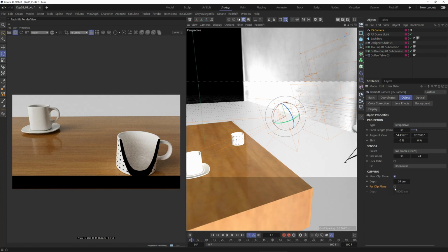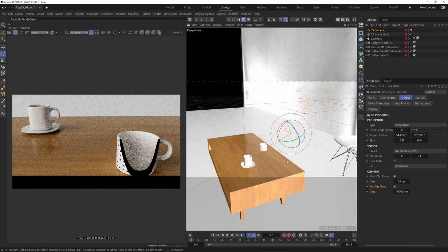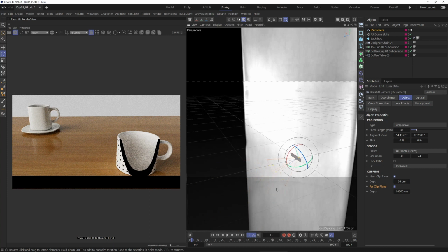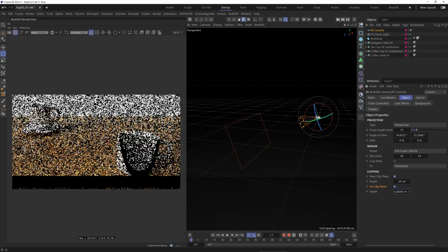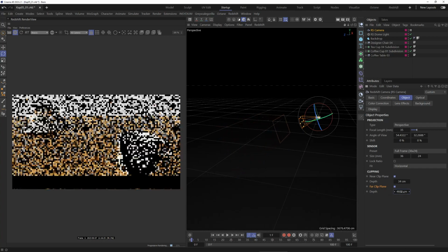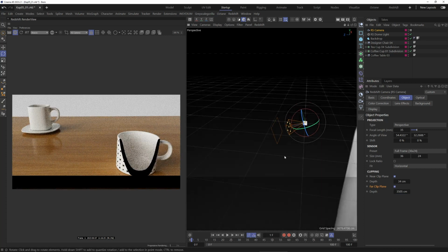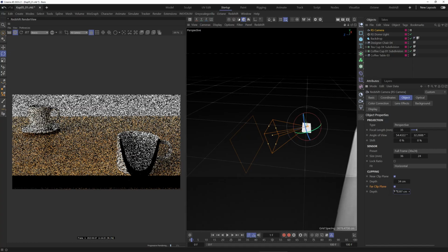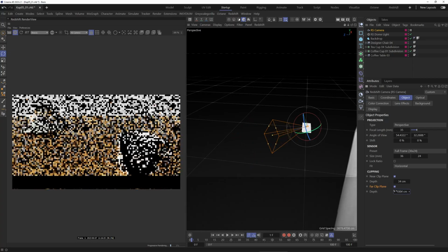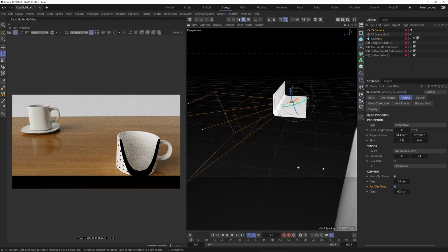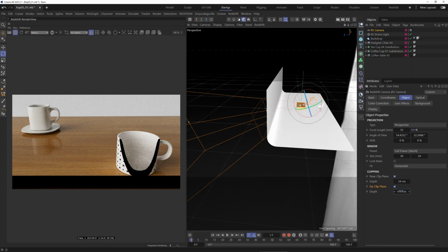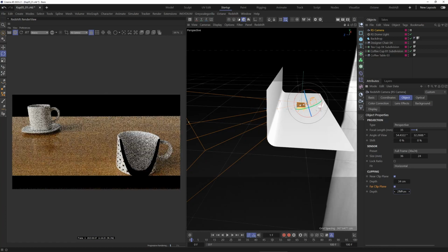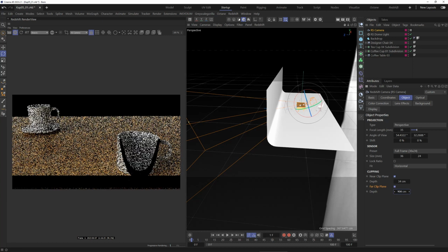We can do the same with far clip plane. I activate it and zoom out further to see the far clip plane. Back here we see the big square. This is the far clip plane. If I adjust this slider we will specify up to where the camera considers the geometry. I move the value and go further back to the fillet. I'm almost there. Let's get a little closer. If I change it slowly, we can see in the preview how we can adjust the camera's field of view.